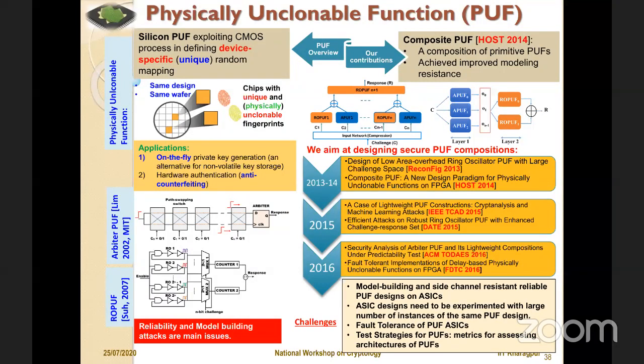But there are many challenges in PUF design. One of the biggest challenges is that the PUF needs to be reliable. The same randomness that you are trying to exploit in the PUF to give you a unique authentication can also make it unreliable. If you apply an input at different time instances, it may end up giving different responses, which you don't want. You also want to ensure that the PUF's response doesn't vary with temperature, humidity, and so on. So you need to make the PUF reliable.